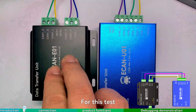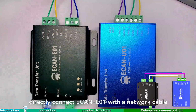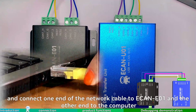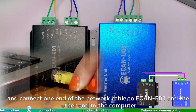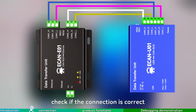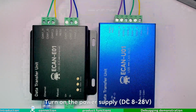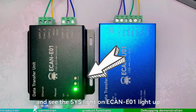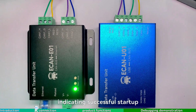For this test, directly connect Ecan E01 with a network cable, with one end of the network cable connected to Ecan E01 and the other end to the computer. After completion, check if the connection is correct. Turn on the power supply, and see the sys light on Ecan E01 light up, indicating successful startup.